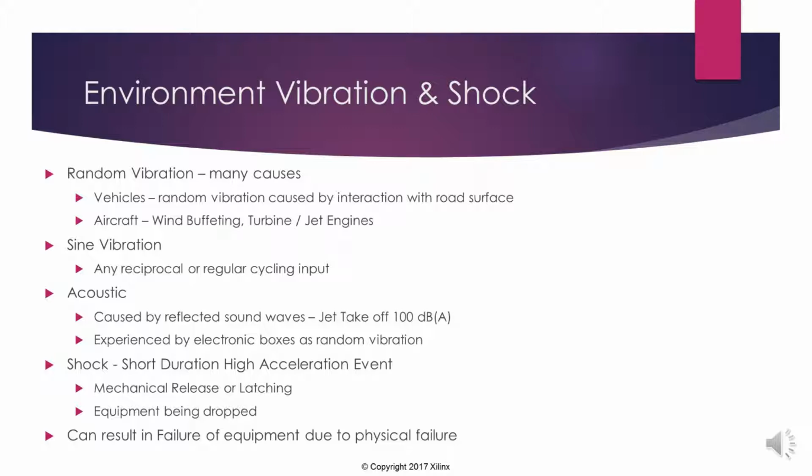But they'd used a one-hot state machine, and actually under vibration the bond wires were bouncing together. The state machine didn't have any protection on it. It was going into an illegal state and locking up. So our defensive design can actually take place in that as well, to ensure that we don't cause any real issues as we design our state machines, which I said we'll look at later on.